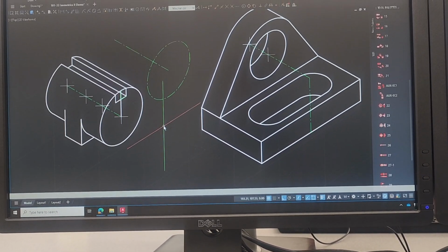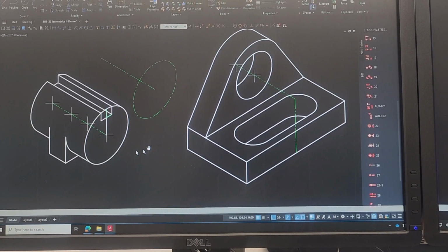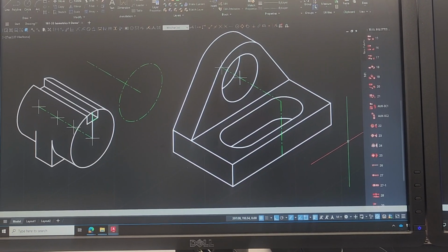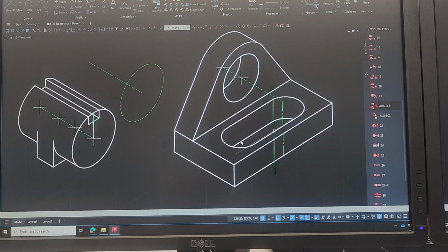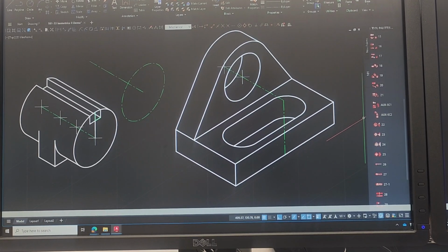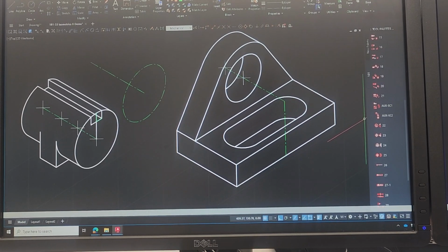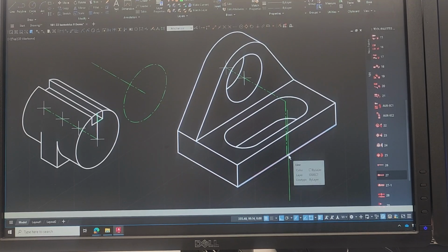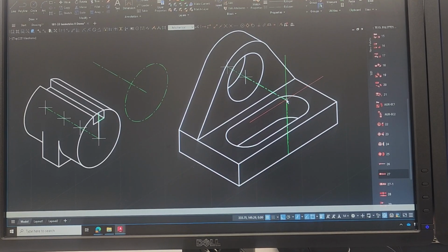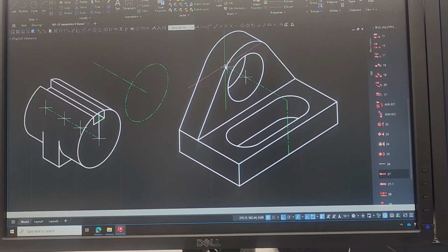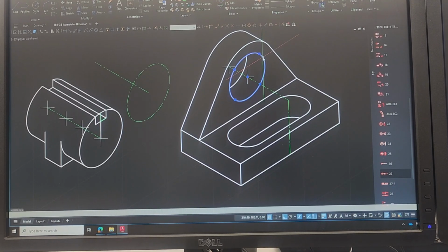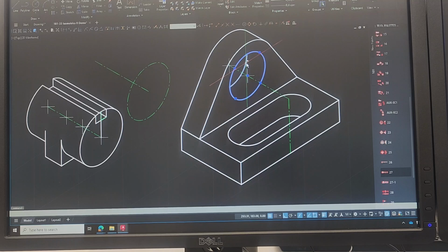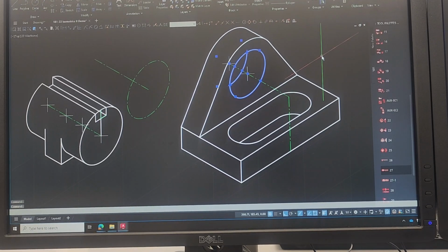So that's really the more complicated of the two problems on here. The other ones on here, get to this guy right here, on here I can just create this slot. Again, I can measure back, I can find the center point here. To find the center point up here, see this 50 over there? What I did was I came to the dead center here, I went up 50, and then I went back to the depth of the object, which was 65, and then I came back forward a distance of 20, and that gives me the location for the center of that, which I can copy back there to get that guy right there as well. See how it's kind of ghosted back there?